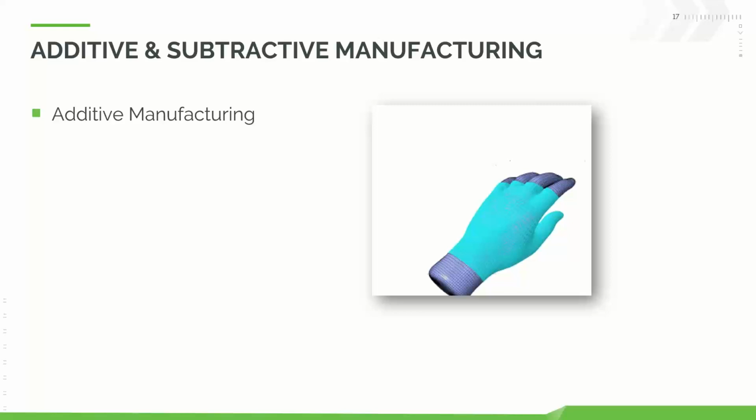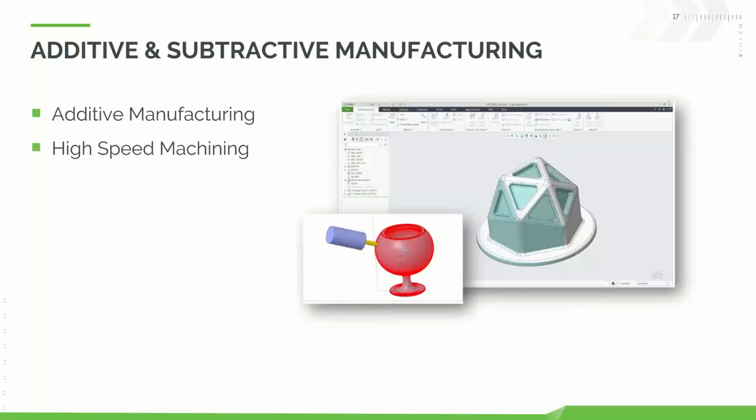You can do variable wall offsets for your formula-based lattices. You're now able to mix user-defined and materialized style supports for a given model. That's all based off of our metal-based printing processes. They all use that materialized support structure, so now you can mix those with your own user-defined. Very welcome improvement in that sense.